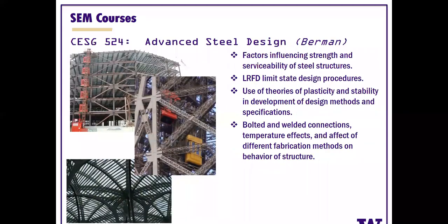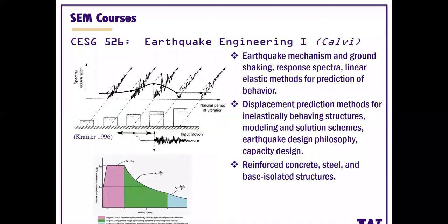Advanced steel design, this is the one I was thinking of when I saw the previous slide. This kind of has to go hand in hand with advanced reinforced concrete. Every graduate structural engineering program really ought to have these two material systems. So this class gets deep into steel design, especially in earthquake regions. How do we use concentrically braced frames, even other systems, eccentrically braced frames, buckling or strain braced frames will even be covered. So a state-of-the-art look at steel systems in seismic regions.